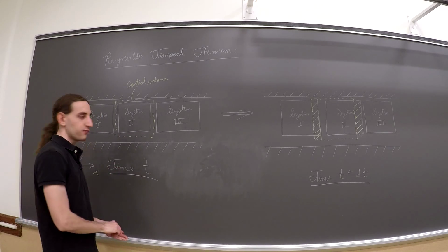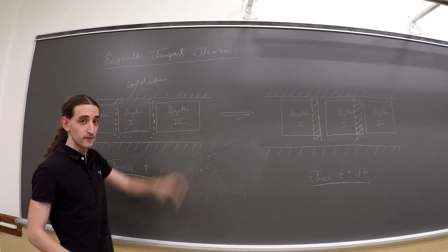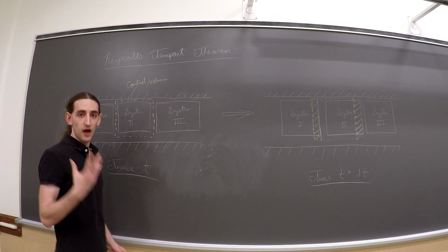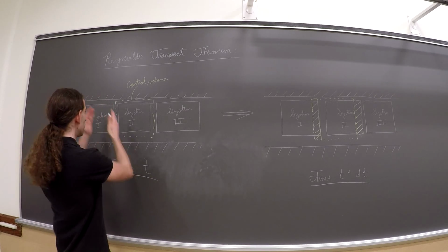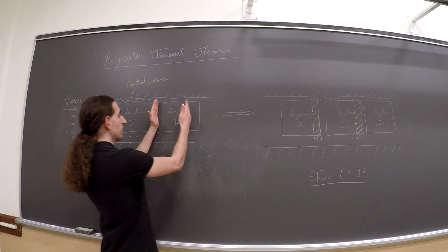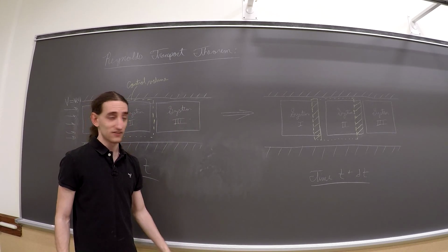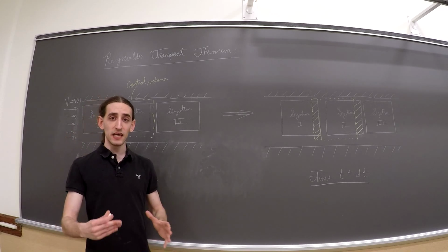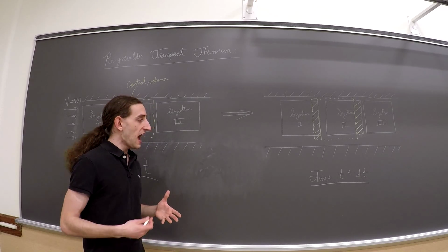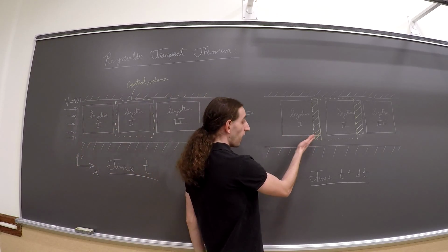As you would expect, if we had this velocity profile coming in and flowing through this region from left to right, you would expect these systems, system 1, 2, and 3, to move to the right as time progresses. As a result, system 1 is going to move into the control volume, system 2 is going to move out of the control volume, and system 3 is going to move further along the system we're analyzing. So at a time t plus dt, where dt is a small amount of time, after a small amount of time has passed, you would expect to see the following scenario.